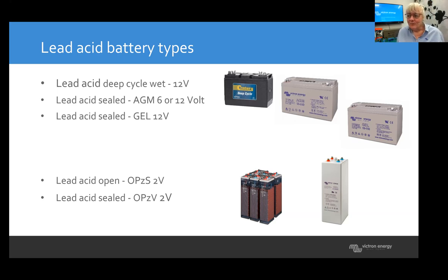The other type is gel batteries, where they've added a gelling compound to the electrolyte. So they've made basically a jello dessert, a really horrible looking gel inside that battery made of sulfuric acid and water. So it's not nice jelly. But again, it's all one solid, semi-solid gel thing. It doesn't slosh around. You can use these batteries on their side. They don't leak. They don't vent ordinarily. But if something goes wrong, they still have an emergency vent.